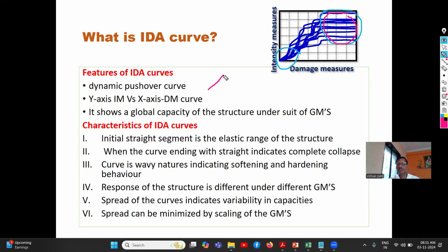and because of the yielding there is cracking, and because of the cracking there is a reduction in the stiffness, and therefore the seismic resistance capacity is reduced, so the curve shows softening behavior. Again, because of strain hardening, there is an increase in the stiffness and the resisting capacity, then a rise. Again, it is softening behavior. Again, there is a rise. Again, softening behavior. And finally,